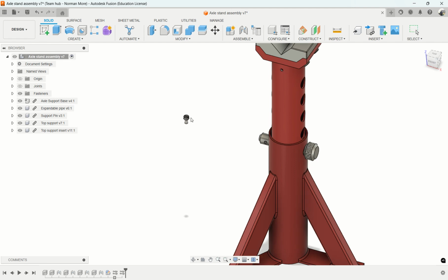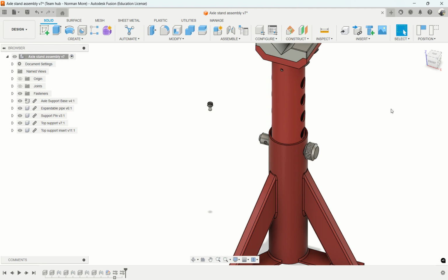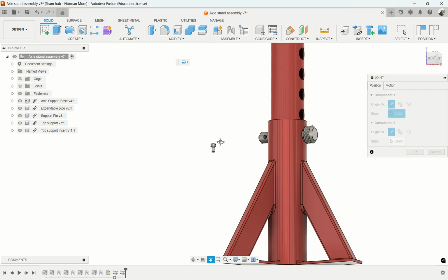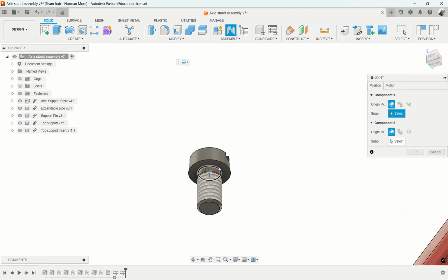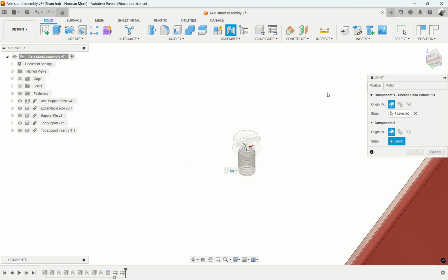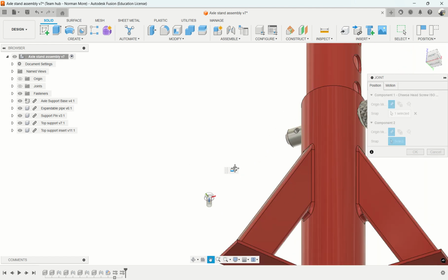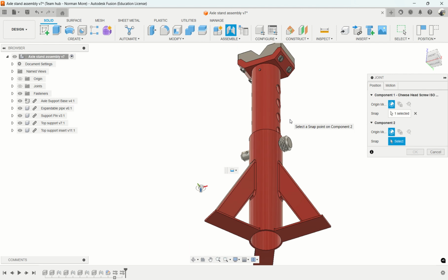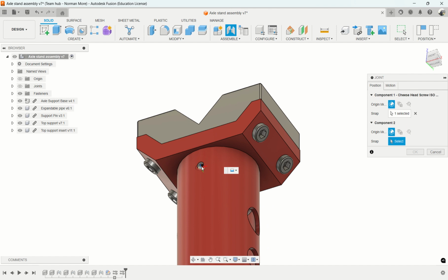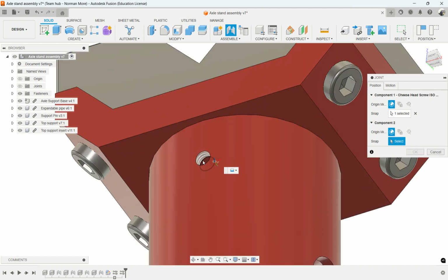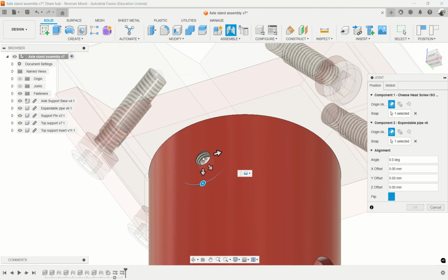So if I pull it a bit somewhere there, then I pick joint, letter J, go underneath this, pick the side which is going to be in touch with the hole, and make sure that I touch the center there.